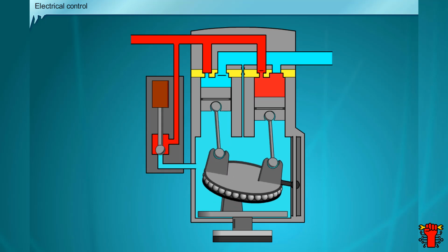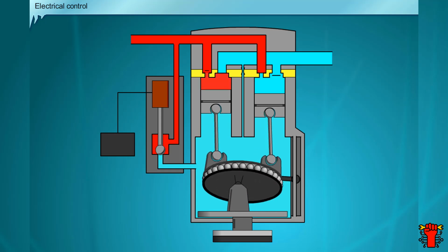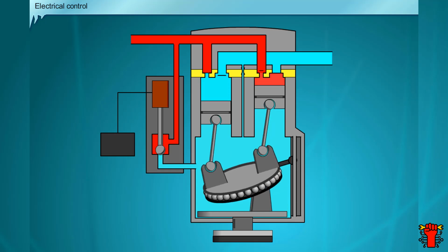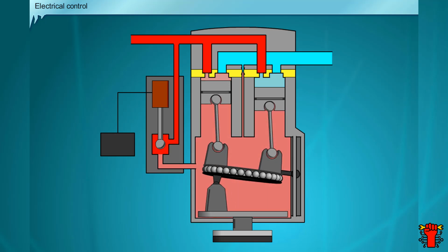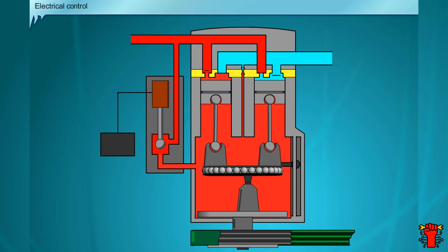Electrically controlled compressors are more advanced. The control valve in this case is not actuated by low pressure, but rather by a control unit. The control range is 2 to 100%. Since the compressor can be controlled to practically zero delivery, it is possible to eliminate the use of the magnetic clutch. It is permanently integrated in the belt drive system. There is an absorber integrated in the belt pulley that acts as a belt guard and safety mechanism against blockage.